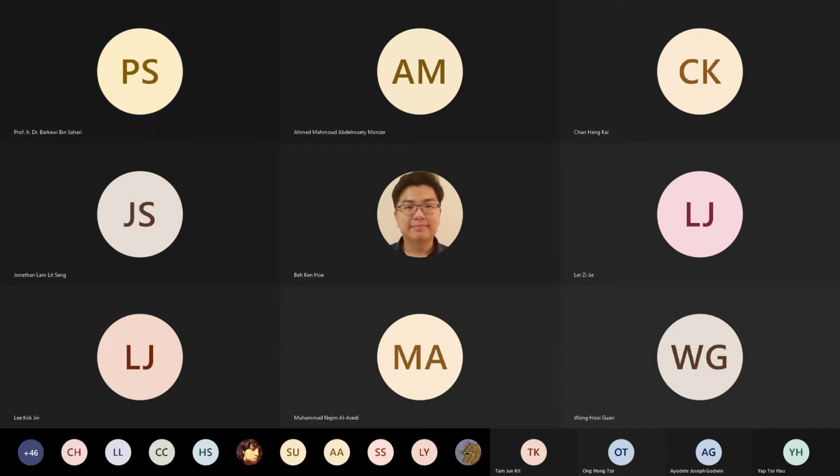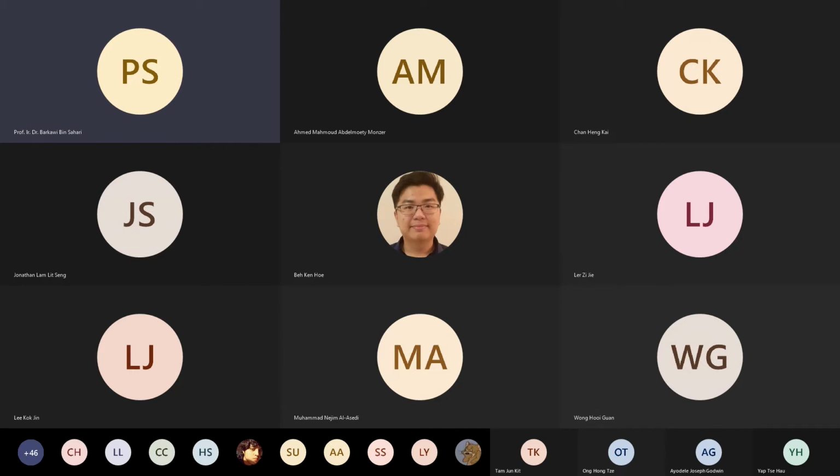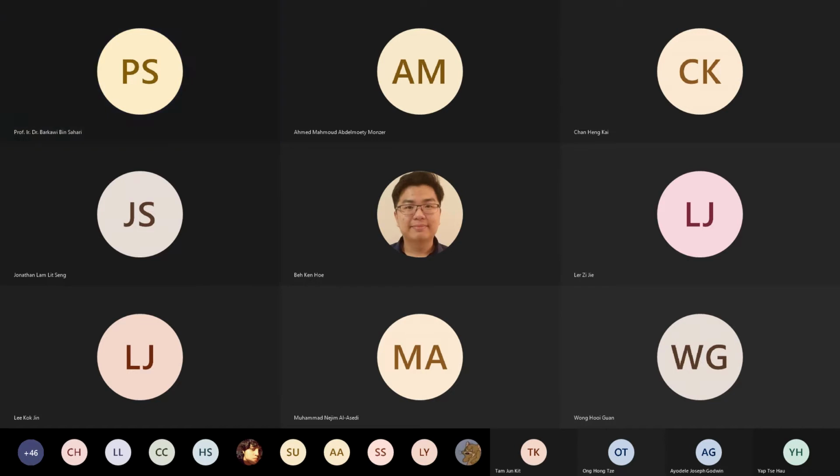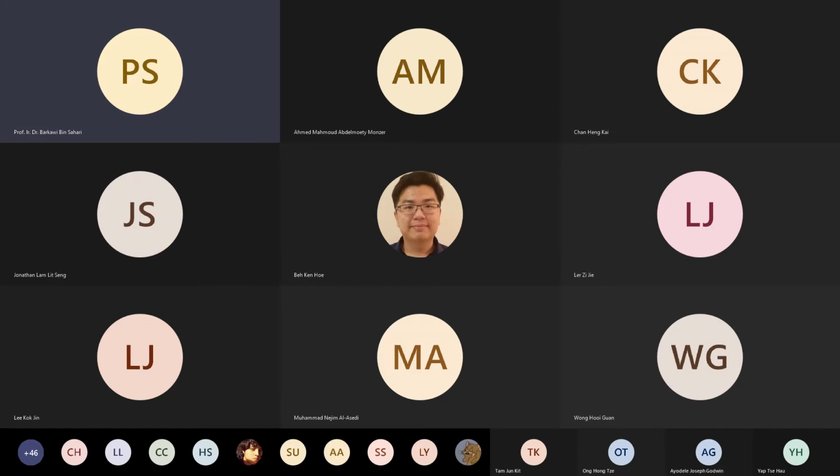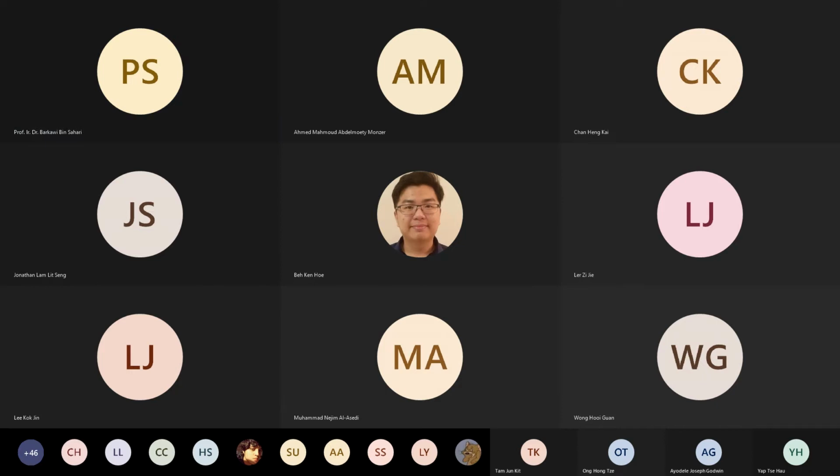Okay, now in the light of effective length, we are looking for the location of zero bending moment. And translated on this simulation, that is zero bending stress. Now let's look at the color fringe for this.